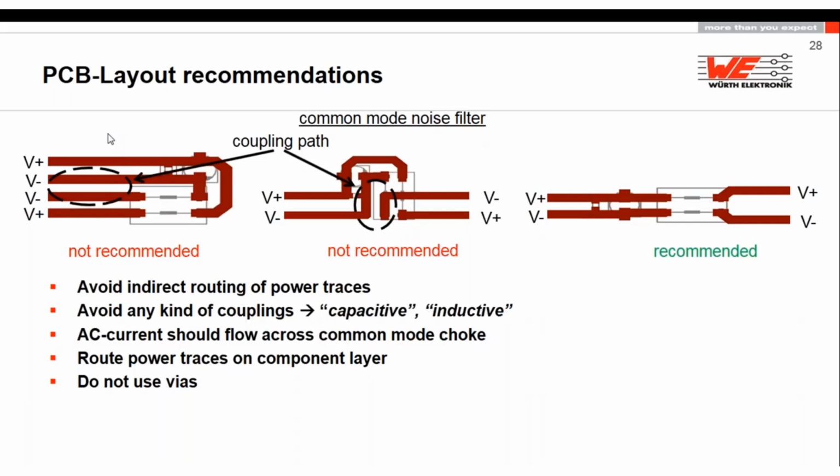Okay, so his homework was now to go home, solder this, and make a PCB solution of these in-air soldered components. But we told him, please don't modify too much on the PCB. Just push a little bit, make a little bit of space to fit these additional three components on the PCB and make them as close as possible to the connector. Well, he pushed away the PCB and he put this common mode choke and these two capacitors as well.